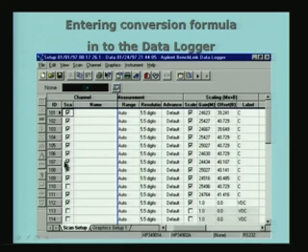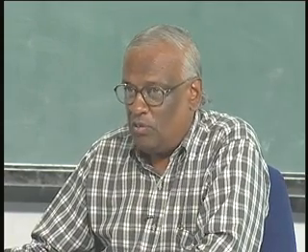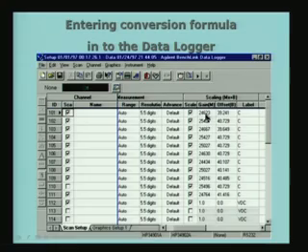So, channel 1 to 9 and then 11 and 12 all have 5.5 digits resolution, and all these are given the gain values. You see that the gain values actually vary slightly from the mean value which I gave earlier. 24623 is the first one, this is 39.241. You see that the offset and the gain both are slightly different for this thermocouple.